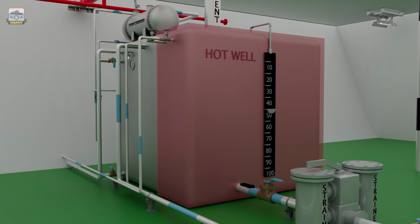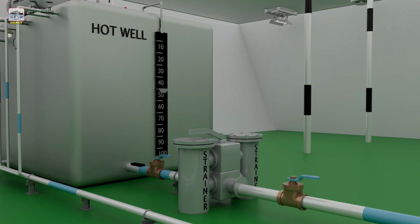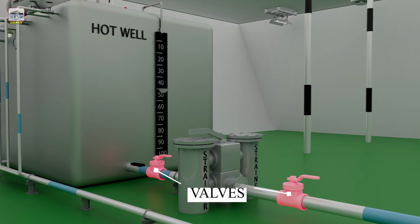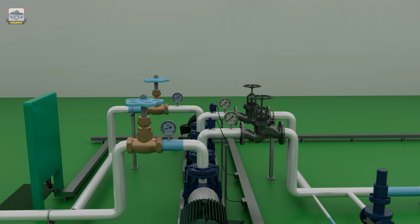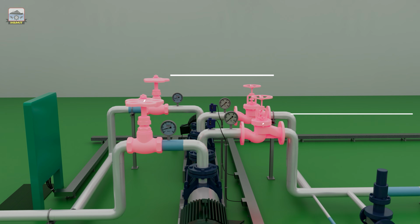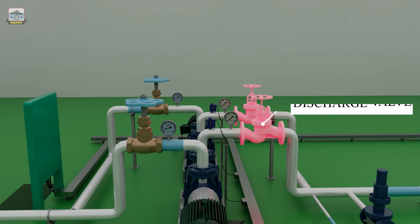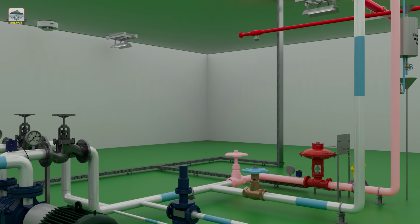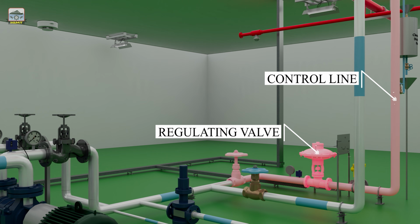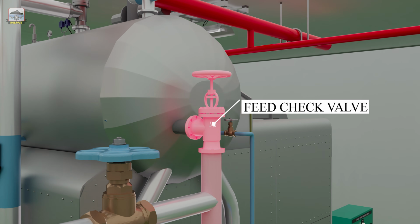The feed water from the third chamber of the hot well is sucked through the strainer by the feed pump. The strainer can be isolated for maintenance purpose by these two valves fitted at the inlet and outlet sides. The pump can be isolated by the valves provided in the suction and discharge sides. The discharge valve is a non-return valve. The discharge branches into many. One control line passes through a feedwater regulating valve and a feedwater check valve into the boiler. Always this control line is used.